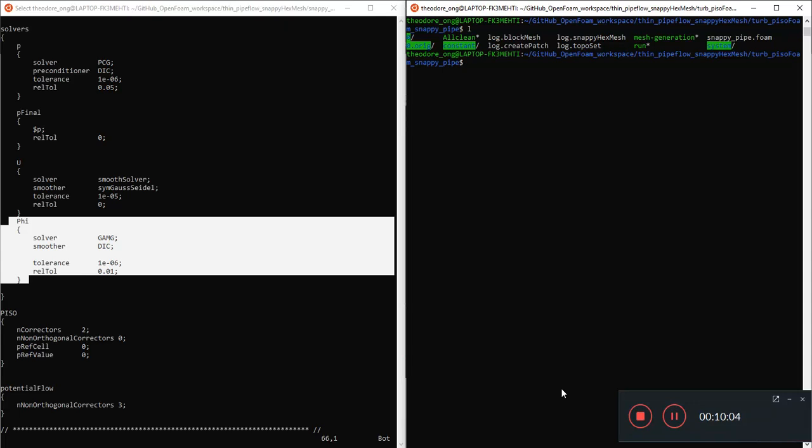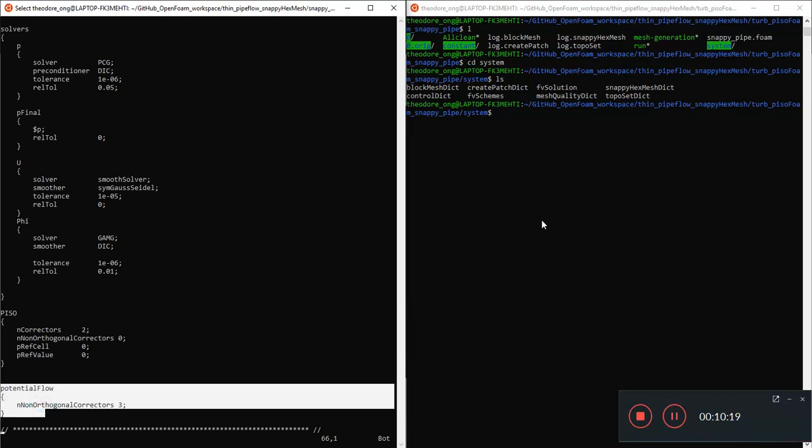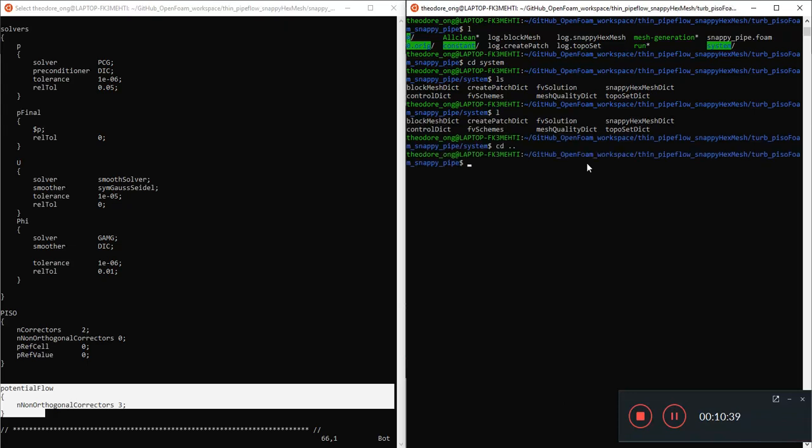Since we have time, we're going to run potentialFoam on this thing first. So cd system, vi. Oh wait, yes. I'll try and stay on task. Maybe next time, when this run finishes, we can do a step-by-step comparison and copy the relevant code over to incorporate potentialFoam into the running of this file. But for now, we skip it first. Anyway, we'll just do a dry run